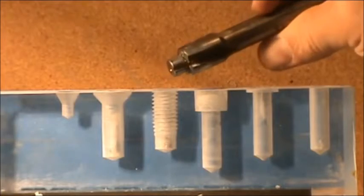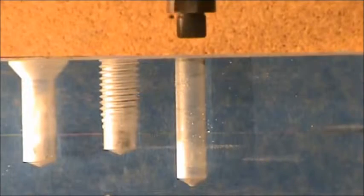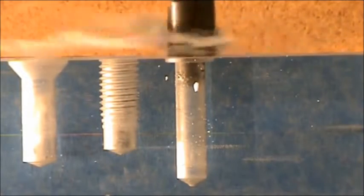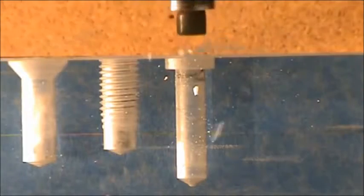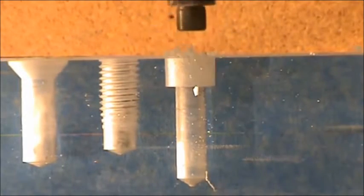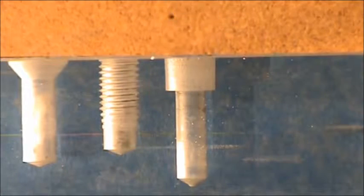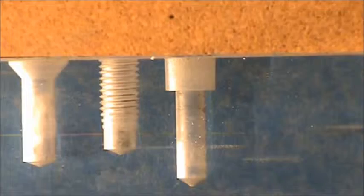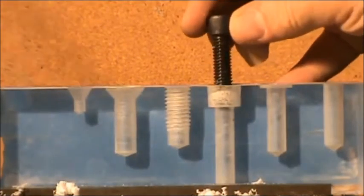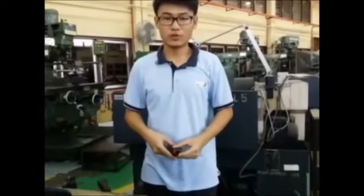Then counterboring. It is used to make a hole for a socket head cap screw. First we need to drill the hole a little bit, and then we continue to the depth desired. So that is the socket head cap screw. That's all from me.